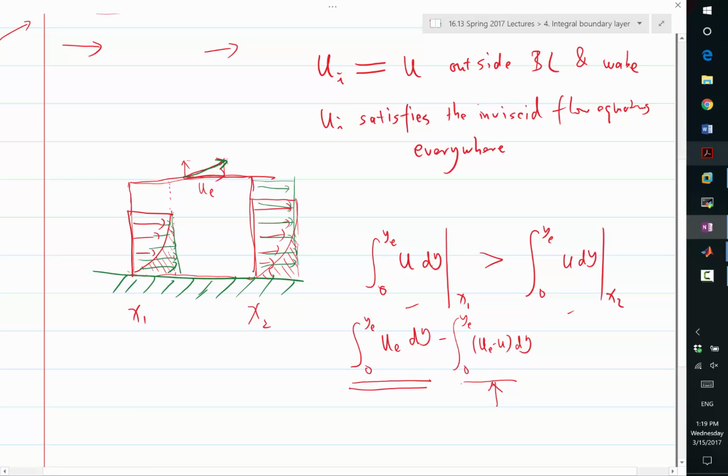So, for the inviscid equivalent flow, can there still be no mass flux across the wall? Okay, we said there is a mass flux out of the top boundary of the control volume because the red and green have to be the same at the top wall. And the imbalance for the inviscid velocity, the green velocity, through the left and right has to be much less than that of the true velocity.